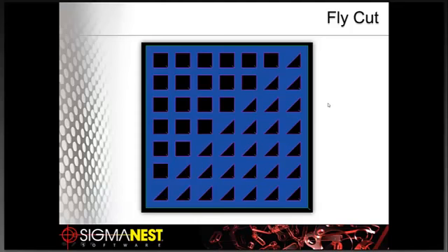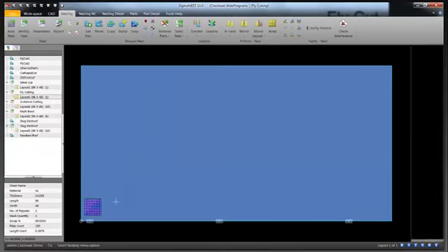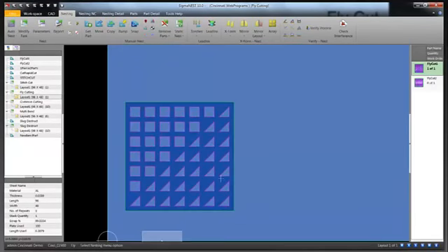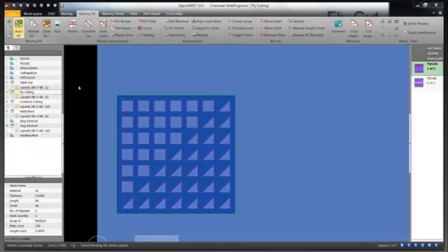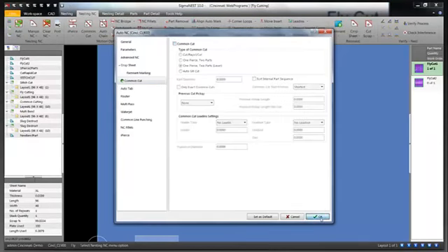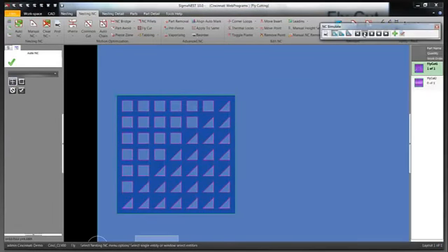The next topic is fly cutting. It's not one that's used all that much because of the part geometry itself, but fly cutting allows you to speed up cutting on repetitive patterns like the part that you see here. So when we have a row of lines or geometries, even on a hexagon, we're going to notice that repetitive pattern within the product and then be able to just cut straight up and down. Now what we do though, which Seth is getting ready to show, without using this function, we're going to pierce in each hole and cut around the contour.